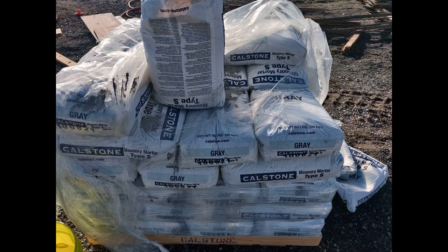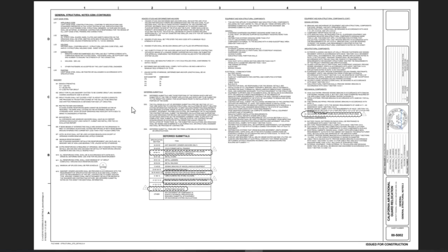Deliver cementitious and other packaged materials in unopened containers, plainly marked and labeled with manufacturers' names and brands. Store cementitious material in dry, weathertight enclosures or completely cover. Handle cementitious materials in a manner that will prevent the inclusion of foreign materials and damage by water or dampness. Store sand and aggregates in a manner to prevent contamination and segregation.